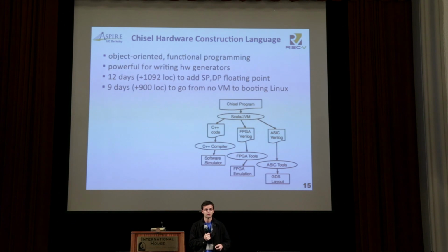I was able to leverage Rocket's page table walker, their MMUs, their connections to the memory system, but I did have to rewrite the load store unit. I had to hook up all this stuff and make sure that Boom could understand all of this. Make sure that you're not forwarding a store to a load. You have to make sure that's a physical address. But that only took me 9 days.